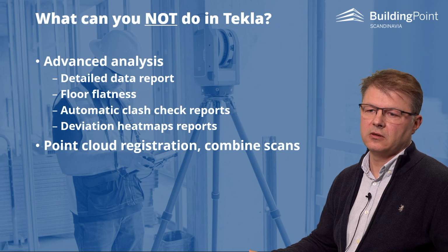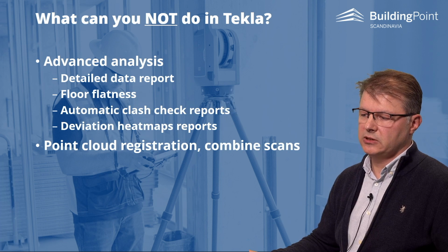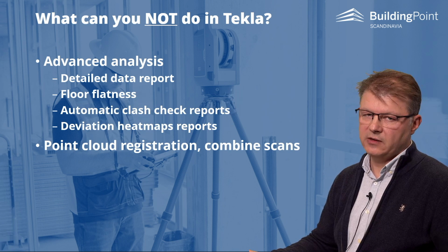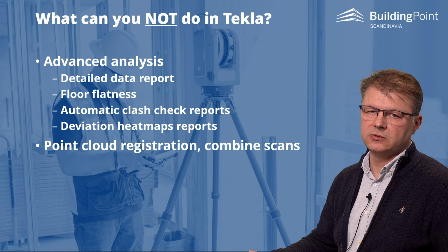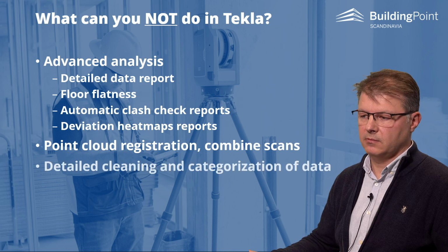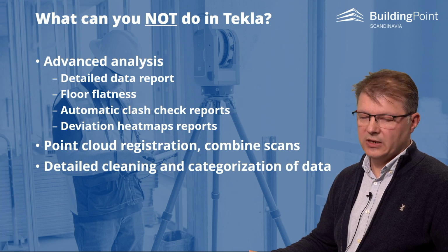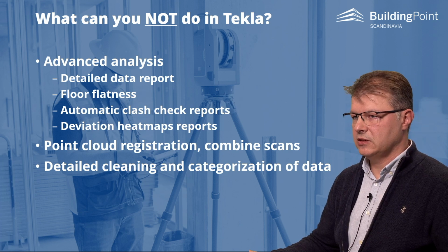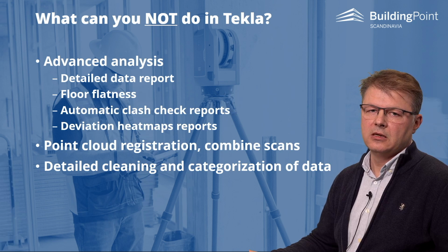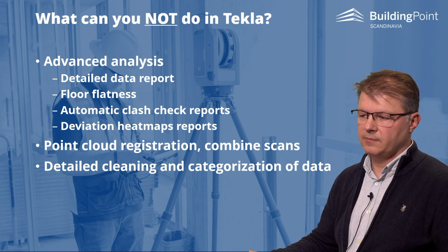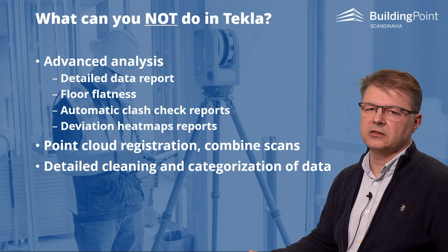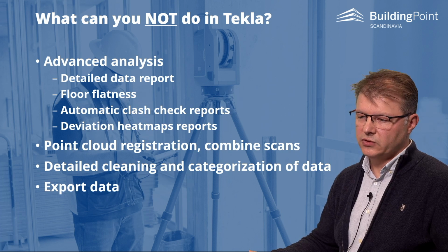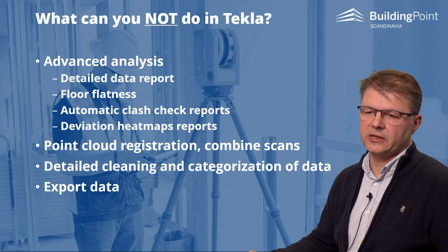You cannot use Tekla for point cloud registration and combining the scans. It's going to be separate scans. You have to do it in the FieldLink first, or you can use, of course, RealWorks to combine the scans and georeference them. You cannot do the detailed cleaning in Tekla. I showed that you can do some cleaning and fitting in point cloud engine, but for detailed cleaning, categorization and stuff like that, you can use RealWorks. And of course, you cannot export point cloud from Tekla Structures.